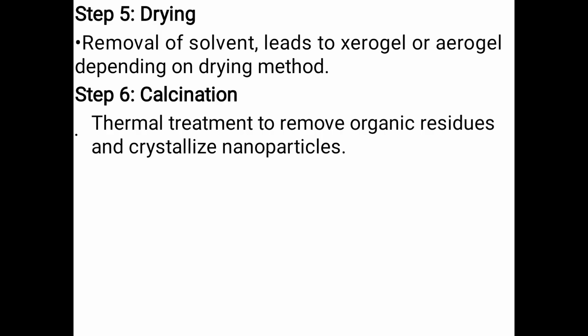Step 5 is the drying process, that is the removal of solvent leading to xerogel or aerogel depending on the drying method used. Step 6 is the calcination. Here thermal treatment is applied to remove organic residues as well as crystallize nanoparticles.